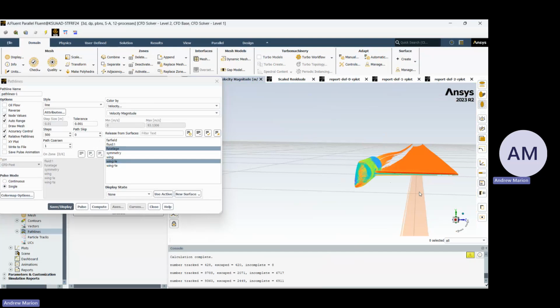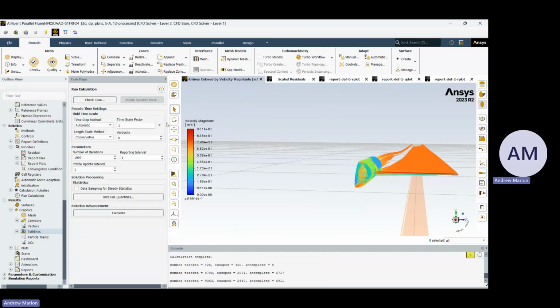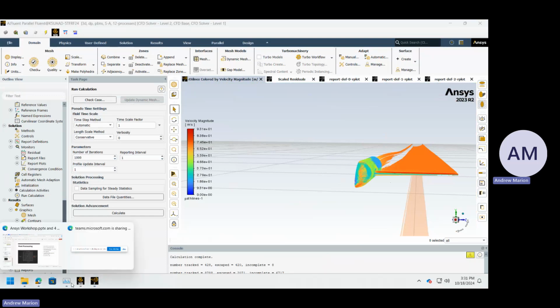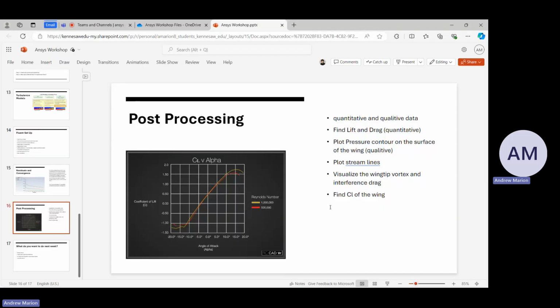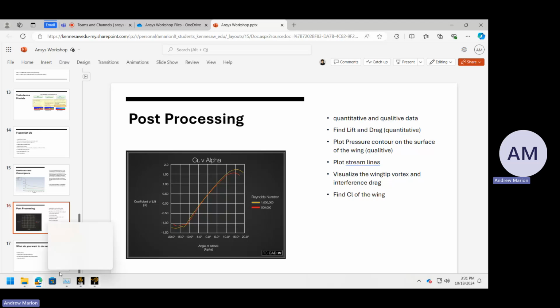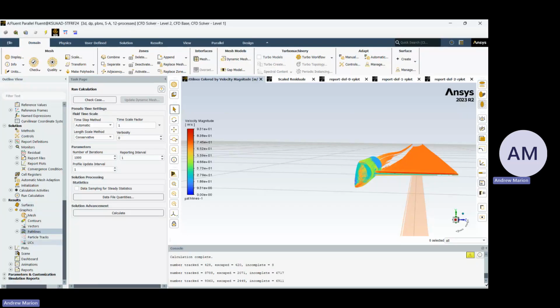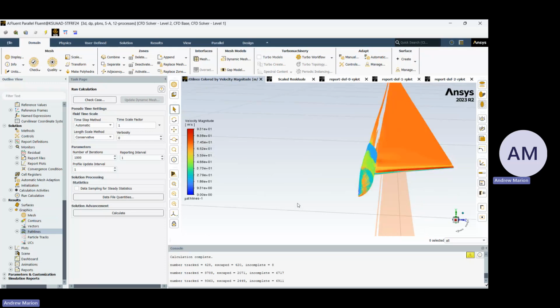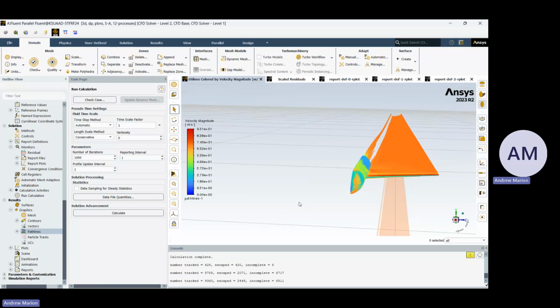So it's a bit of a paradox, because in order to have lift, you need induced drag, but induced drag saps away the energy from the lift, so you have less lift. So it's a weird little paradoxical balance act with aircraft design where you want to minimize induced drag as much as you can to get more efficient lift, but if you completely get rid of induced drag, you can't fly.